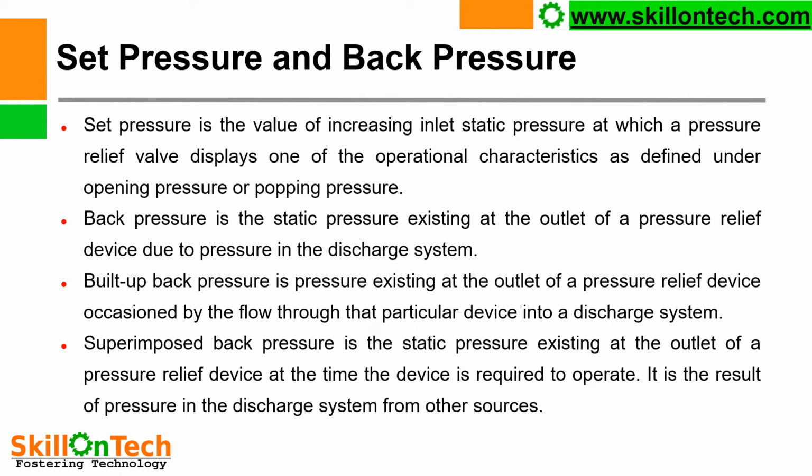Set pressure and back pressure. Set pressure is the value of increasing inlet static pressure at which a pressure relief valve displays one of the operational characteristics as defined under opening pressure or popping pressure. Means at a set pressure, the safety valve will pop up and it will relieve overpressure from the safety valve.